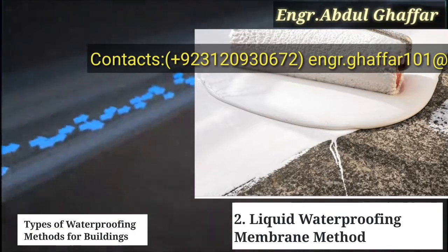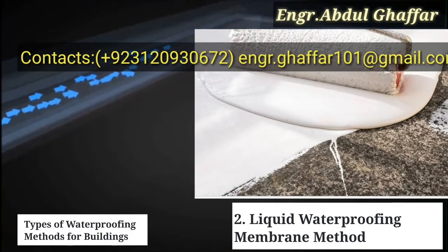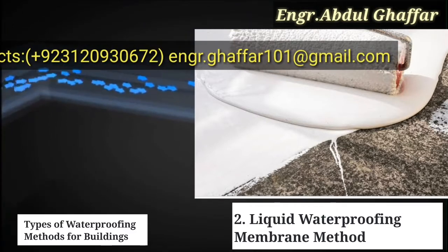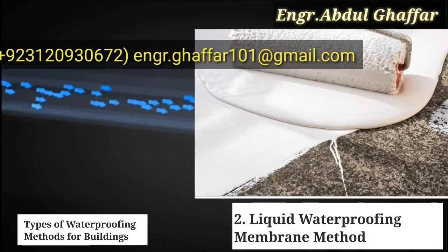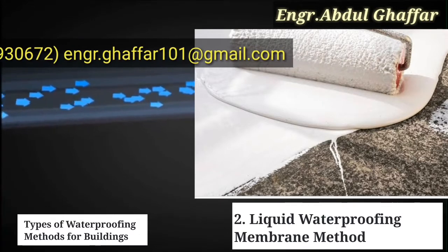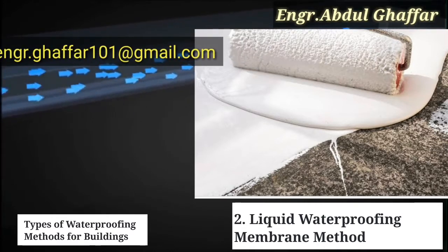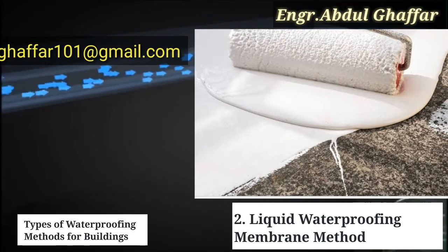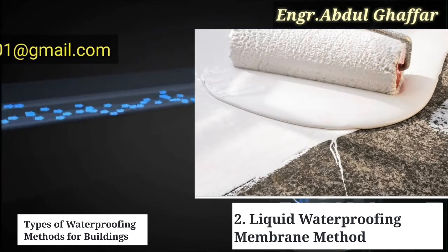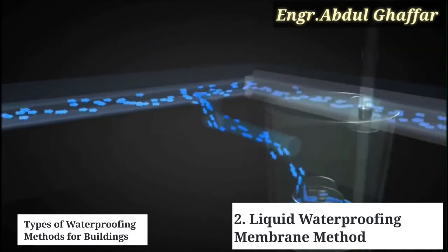The elongation properties of the coating can reach as high as 280%. The durability of the waterproofing coating depends on what type of polymer the manufacturer used for making the liquid waterproofing. Liquid waterproofing membrane can be a spray-applied liquid membrane composed of polymer-modified asphalt. Polyurethane liquid membranes in separate grades for trowel, roller, or spray are also available from various manufacturers.